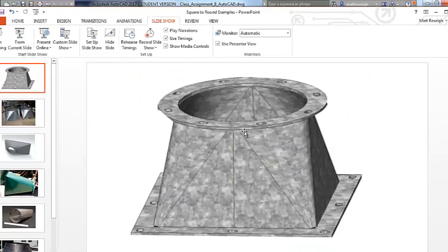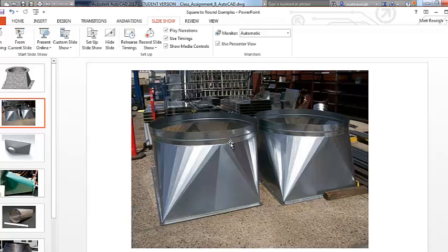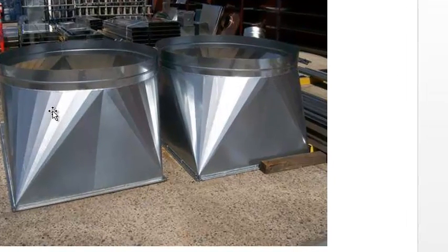What we're looking to define here is all those break line segments that we see in this one. We need to determine these true lengths, and we don't get that by looking at a top view, and we don't get that by looking at a front view because of the shape of the object. If I'm looking at the top view, there's definitely a lot of distance that those are traveling from the round to the square that I'm not picking up. I have no depth perception when I'm looking at a top view. And when I'm looking at a front view, I don't pick up the same kind of scenario where I transition from the square point to something that's round. It's kind of falling away from me in the view. I'm not picking up accurate lengths in the front views or top views. So I have to interpret both those lengths using the Pythagorean theorem to give me true lengths.